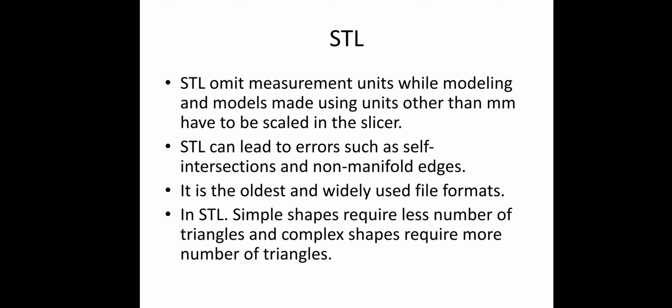If other units are used in the slicing software, we have to scale it again. While modeling, if models are made using units other than millimeters, they have to be scaled in the slicer. STL can lead to errors such as self-intersections and non-manifold edges. It is a major drawback of the STL file format. It is the oldest and most widely used file format.